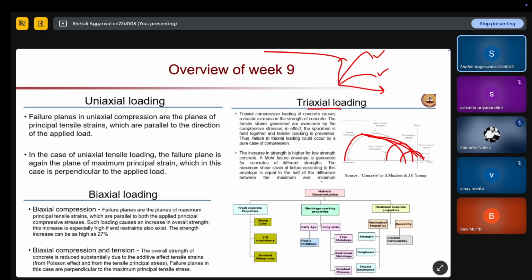Now, when we are talking about the stress strain curve, it gives me the modulus of elasticity, rupture and all those things. The area below this curve tells us about the toughness of our concrete. Toughness is related to the ductility of the concrete system. The more the area under the curve, the more the toughness, the more the ductility, and we can say the lesser the strength value.